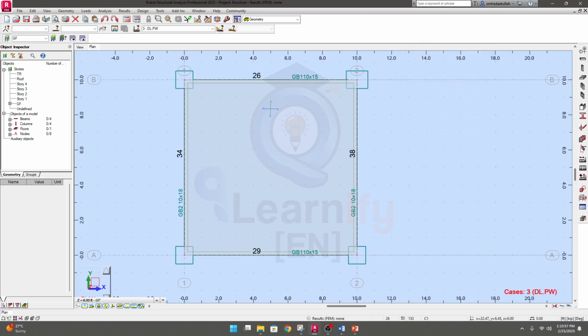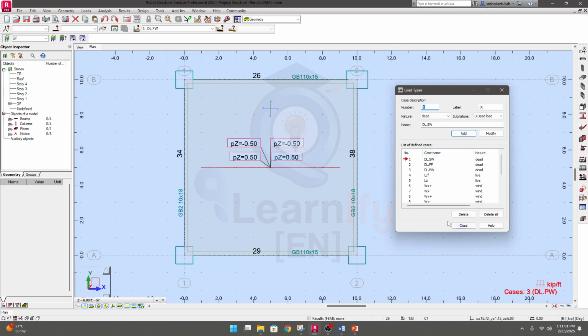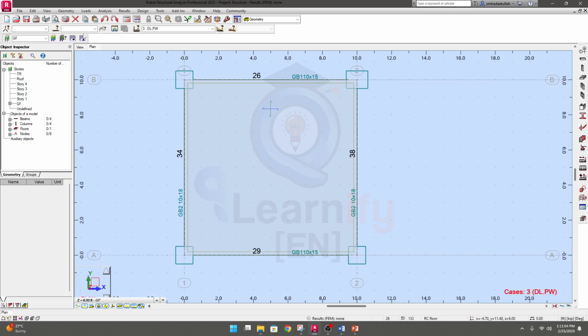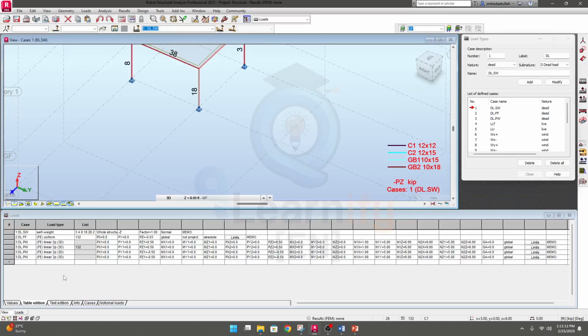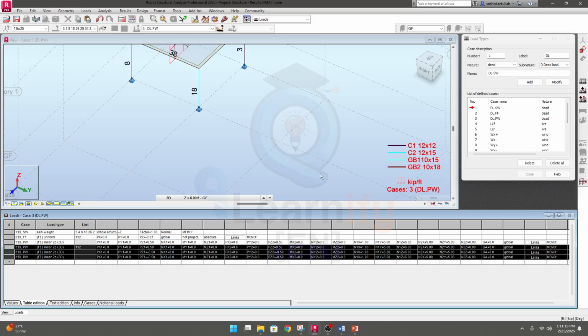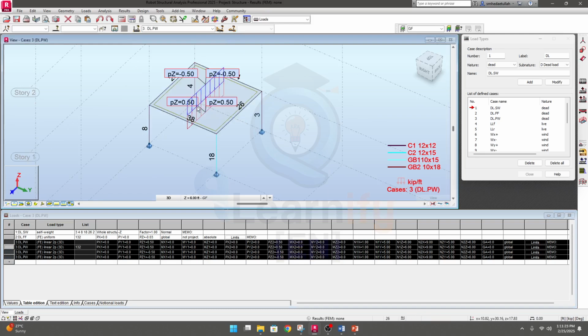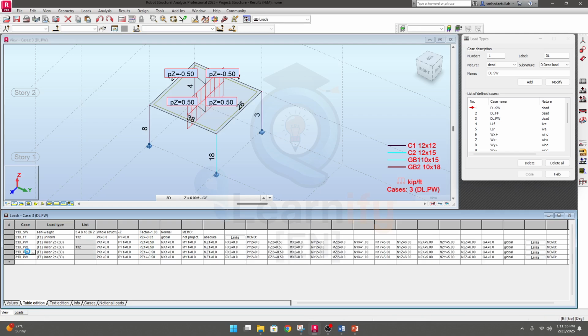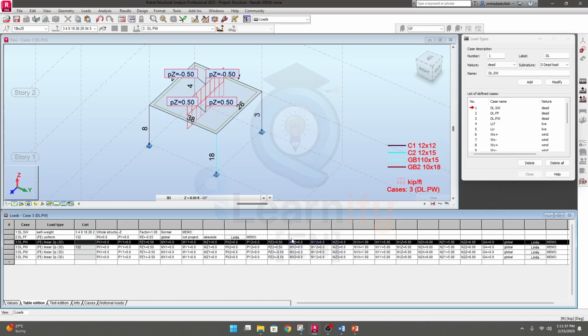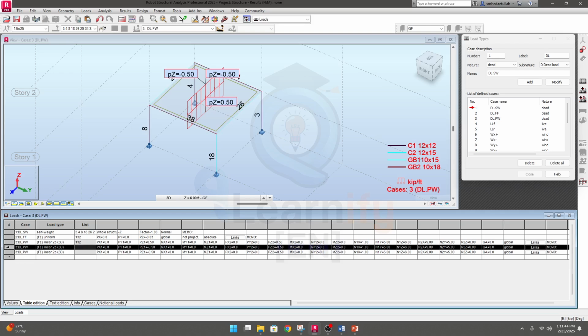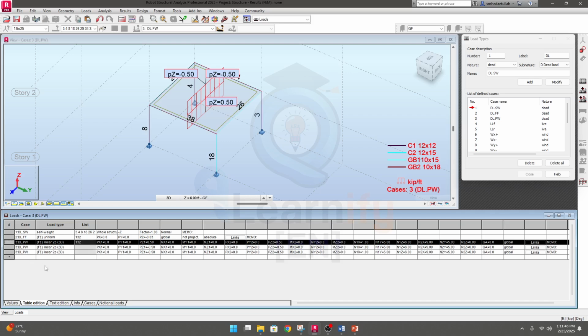Again, I can go here, load type. Okay, to see it, now I'll go here, our loads, and here you will see that I have assigned that load multiple times. So you can see how many times I have applied that load. Every time I clicked, this load was assigned, for 4 times actually. And some loads are working in the upward direction because we provided the plus value. Now I will close that load first because this value is 0.5. Select and delete. Then I'll close this load also.